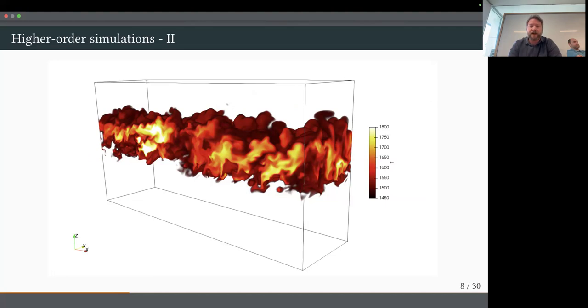This is one of our first attempts at direct numerical simulation. And this is the kind of work that informs turbulence chemistry models in RANS. So this is a DNS with reacting flow. And from that, we can tune our ideas about how to build some more design appropriate models for the RANS world.